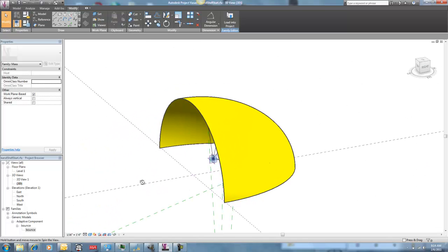And this is actually a nested curtain panel family. So you can see we've got our black line that was our original line, and then our green line, which was our bounce. And if I open up my curtain panel here, you'll see it's got more geometry in it. If I go edit family, in my curtain panel I've got 2 angles. One is the angle from the target coming into the surface that it impacts, and then coming out from it there is the bounced ray.